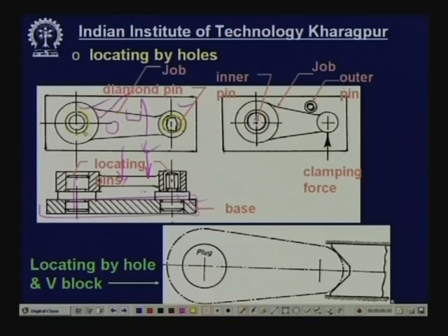But one thing to be noted is that this distance of the holes is assumed to be fixed, but it will not be fixed. There is always a machining allowance. Therefore, a small gap between the pin and the hole has to be maintained to allow for this variation or tolerance, but it cannot go in this direction or that direction. Suppose instead you make the pin here and here, then you reduce here, which means a gap. These are called diamond pins.